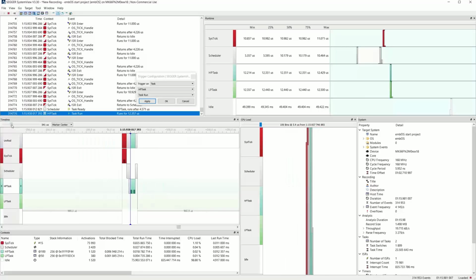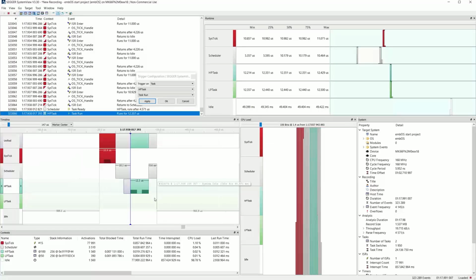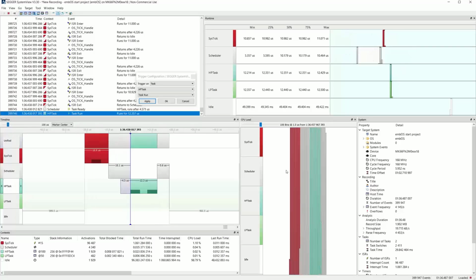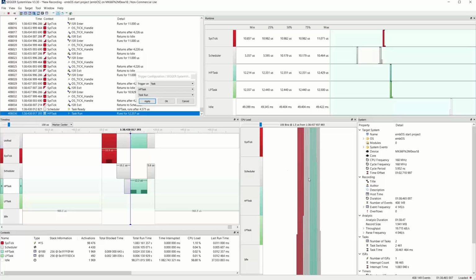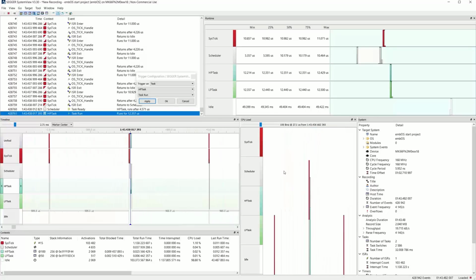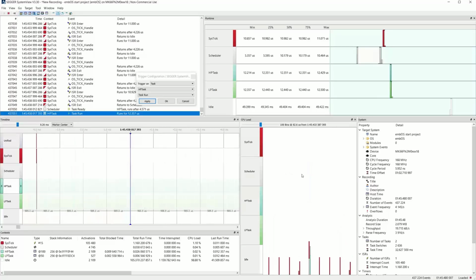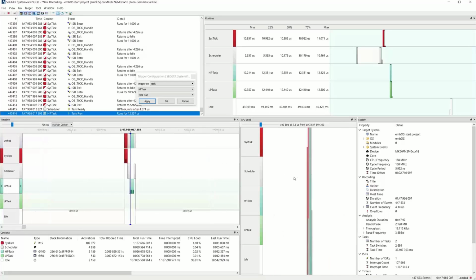And you can make sure that in all your different tasks, I mean, this is a very simple example, but if you have like 10, 12 tasks, you can make sure that the timing is all right. You can make sure that you don't have too many deviations in terms of how often these tasks are called. Over here, you have an indication of the CPU load. So we can see the white space is idle, so we see we have lots of CPU load left.